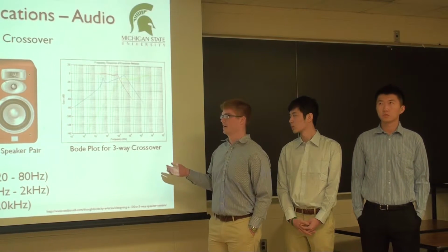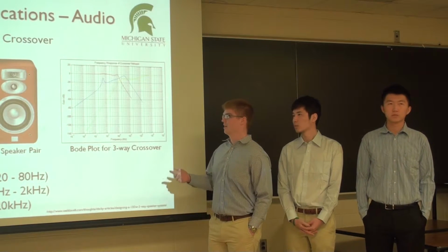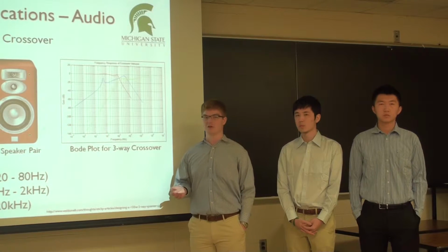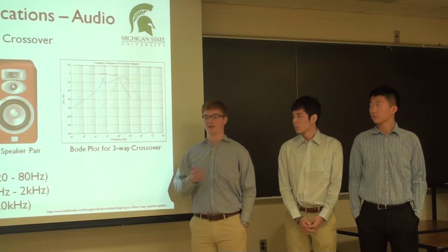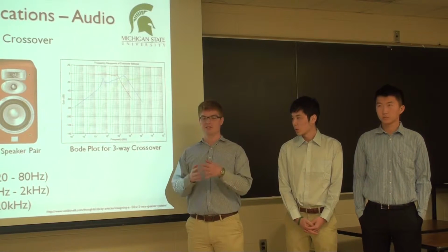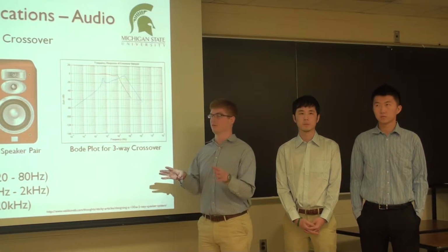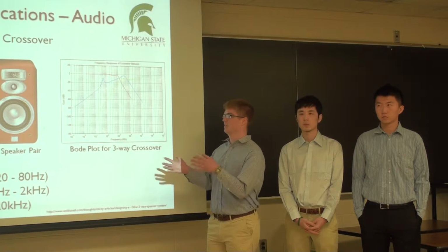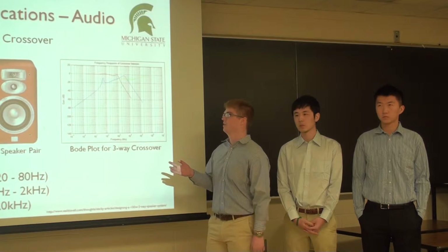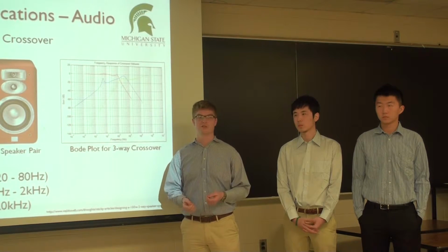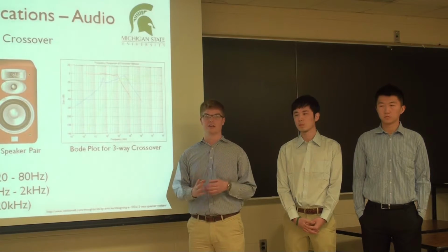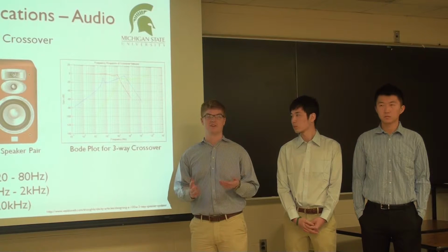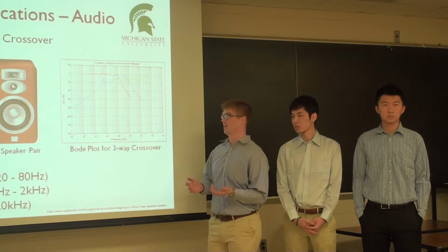A way that this is actualized is by developing what you call a crossover network, which is essentially 3 different filters that take an input signal that's common to all 3, and then they output different frequency spectral content to each speaker. The reason this is necessary is because it's really difficult to design a driver or a speaker that can play all frequencies across the audio band.